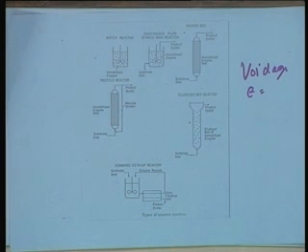Particularly in the case of exothermic reactions, there might be a lot of local hot spots which can inactivate the enzyme. Fortunately, enzyme catalyzed reactions are not highly exothermic, they are usually isothermal, so the problem of heat transfer is not so severe, but even a smaller level of heat generated can be taken care of very easily in fluidized bed reactors.